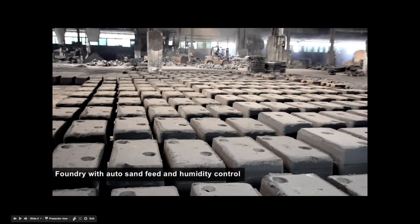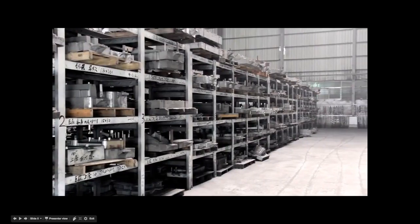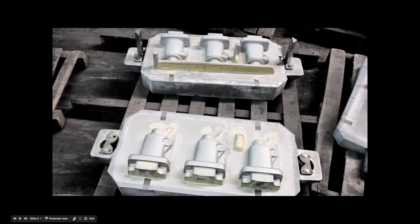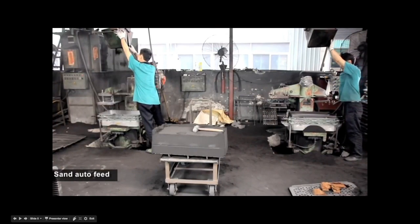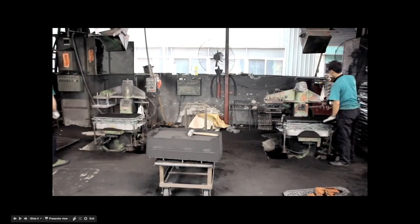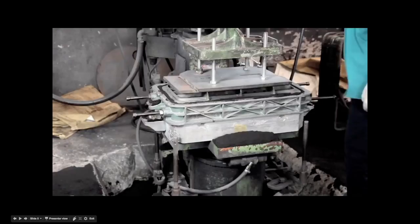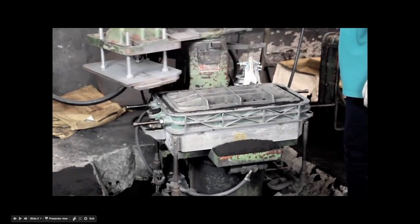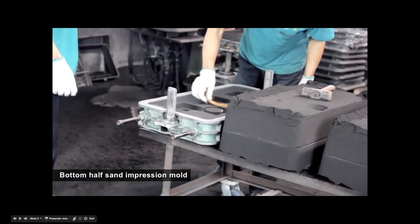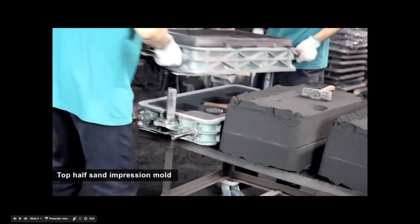Factories specializing in sand casting are called foundries. Here is a foundry with auto sand feed and humidity control. First, a pattern is designed for the mold. Place a pattern in sand to create a mold. Then, remove the pattern, incorporate the pattern and sand in a gating system on both top and bottom half. Remove mold frame and prepare for casting.